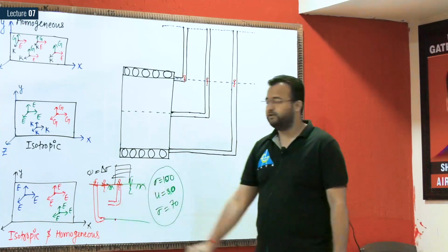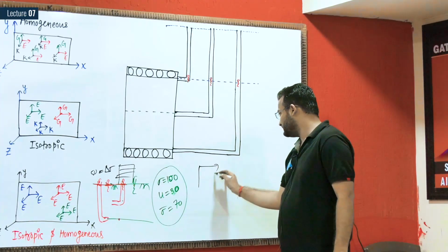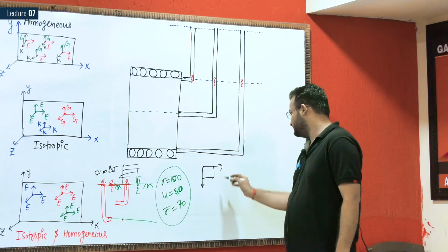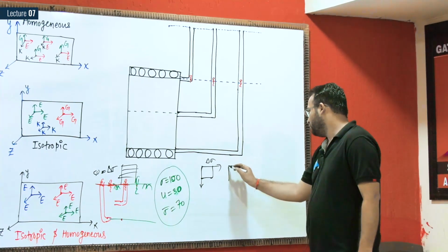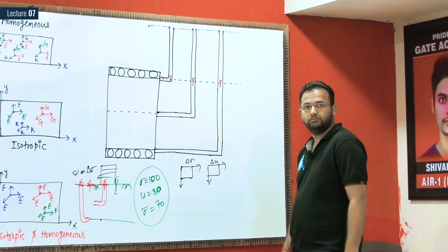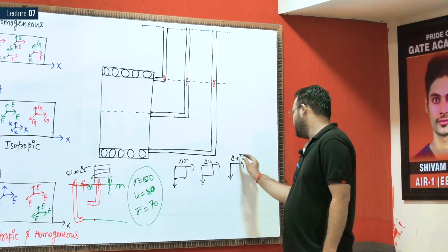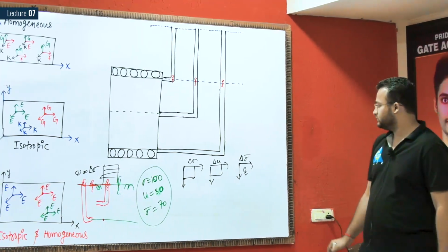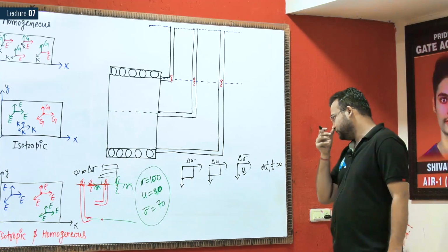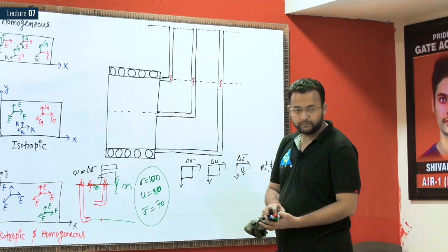The complete value of 50 will be taken by, you see, in the last class we have discussed about the primary consolidation. At T equal to 0, total stress, this is delta sigma, will be completely taken by pore water pressure delta U. Clear? So that time, what is the value of effective stress? Delta sigma bar 0. This is the condition at T equal to 0.